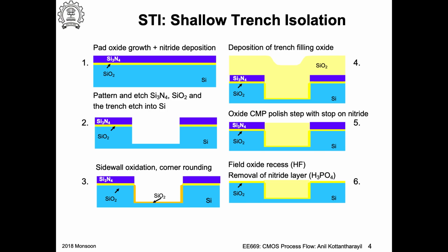Okay, so you etch the trenches. So usually the sidewall is not vertical as shown here, it is slightly slanted, so you will see that on the next slide. And then you remove the photoresist, right? And then the wafer is again subjected to an RCA clean, essentially to prepare the exposed silicon surface for growing a very good quality silicon dioxide.